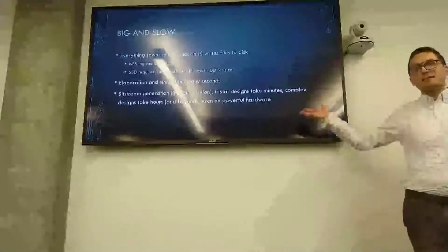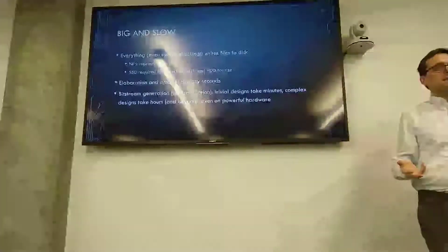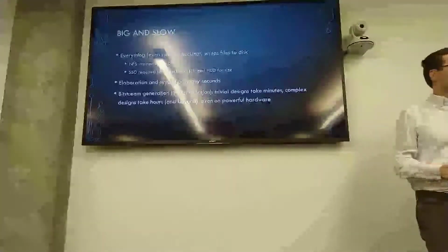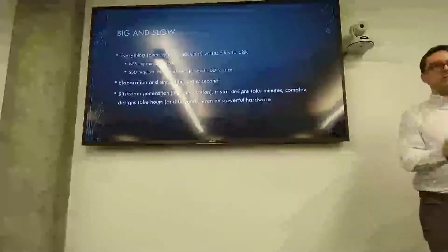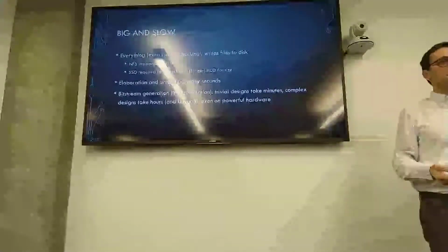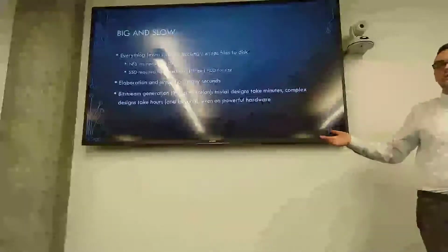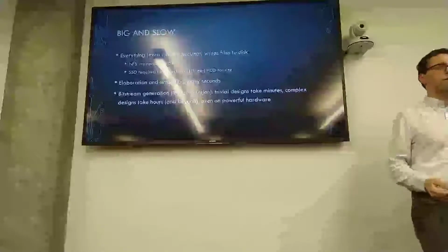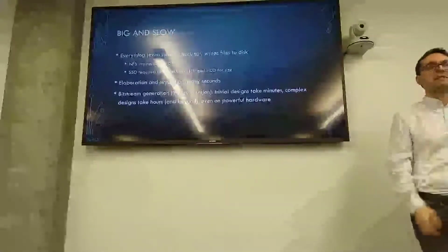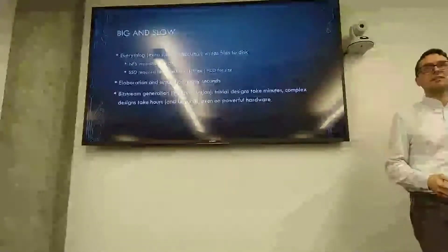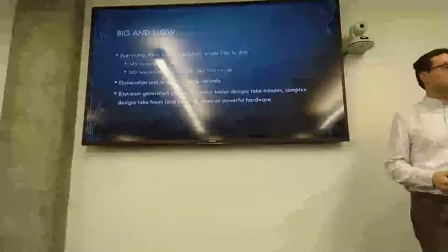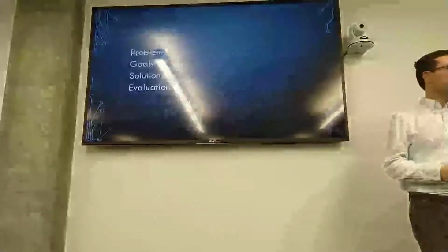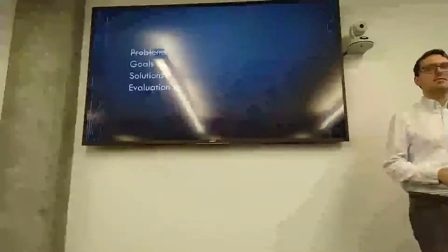One of the main problems is everything's written to disk. Part of the reason is it's written to disk because it's big and it doesn't fit in RAM. But that makes everything slow, and makes developing for people like us difficult because NFS storage doesn't work very well over a connection like this. Bitstream generation takes a long time because it's writing many intermediate files, often the same files over and over again for every different design you do. And for every different change you make, it writes the same files again. So those are some of the problems.